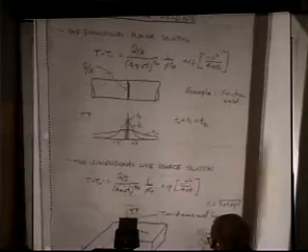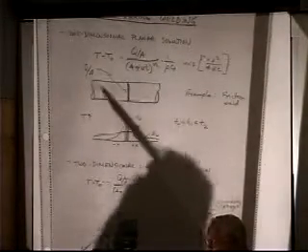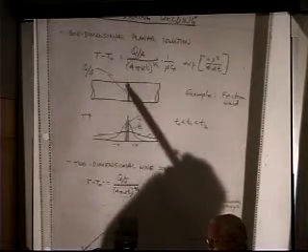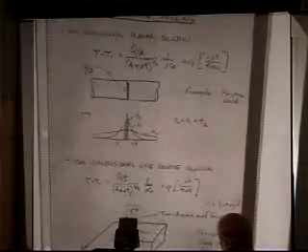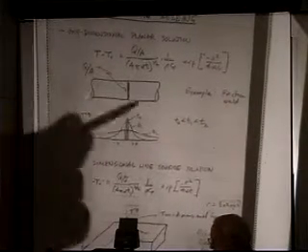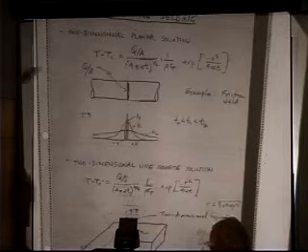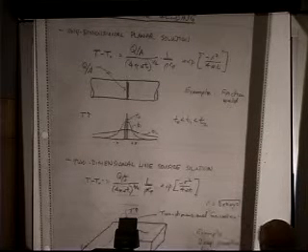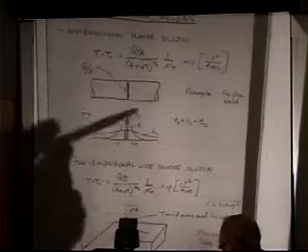But the simplest solution is just a one-dimensional planar solution where I have two bars and I have a planar heat source which has an intensity of some heat Q divided by some area A. So that's going to be a watts per square centimeter type of number. Well, what's this? This is based on something like friction welding. I bring these two rods together and it's a planar heat source. So this is basically just a simple friction welding problem.